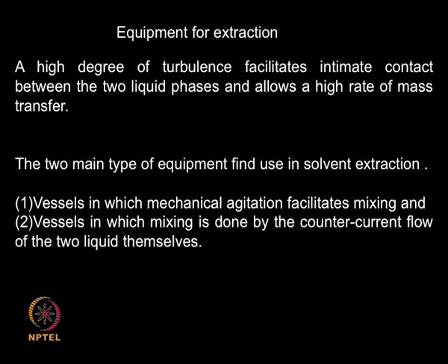So the mass transfer limitations, the movement of the solute from the heavy to light needs to be speeded up. So you need to create turbulence between the two different liquids so that the solute moves very fast from the heavies into the lights. So it is not only the thermodynamics, you are also wanting to improve or speed up the kinetics.